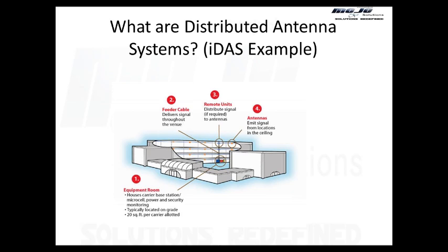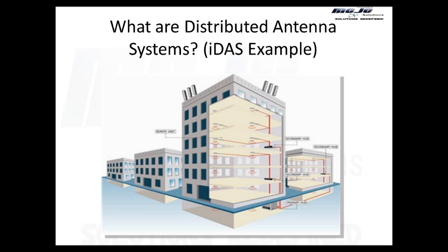In the DAS system, we will learn, based on the building structure and our requirements, how we should deploy DAS, how we should position our antenna, what a floor plan is, what a design plan is, how the iBwave is used, how to run the propagation, how to do the link budget, what the criteria for DAS are, how to calculate the DAS system, how to prepare the RFDS, how to prepare the design in iBwave, and how to understand the design in iBwave. We will not go into detail on some, but we will learn how to calculate the link budget.